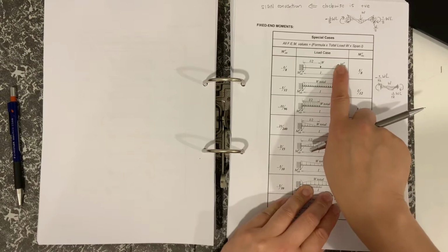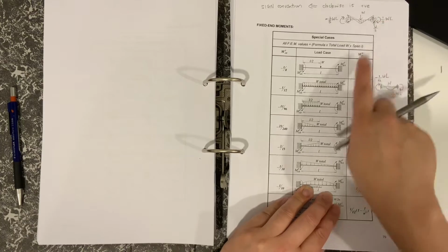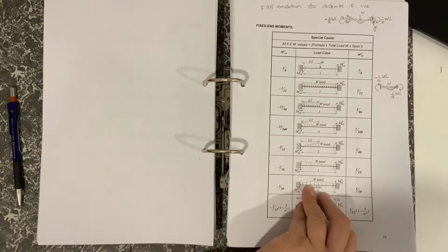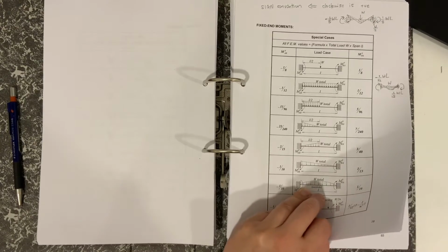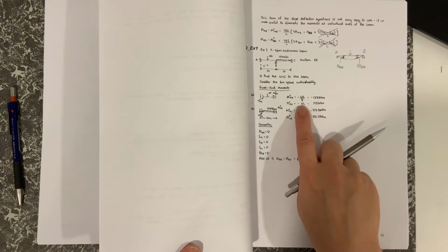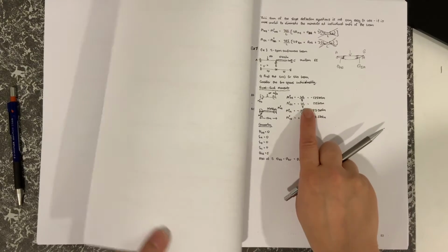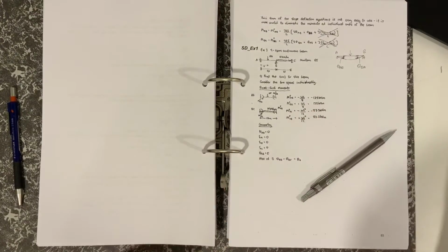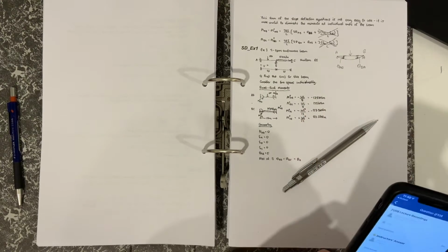Now there's another fixed end moment on the other side, and again we use the same equation. So draw the clockwise arrow, which is also clockwise for the moment reaction. So that and that are the same. MFBA in this case is going to be equal to positive total load times L, which is 100 times 10, divided by 8, and we're going to get 125. By virtue of the symmetry, you didn't actually have to calculate it out. It would just have been the opposite of the other one.